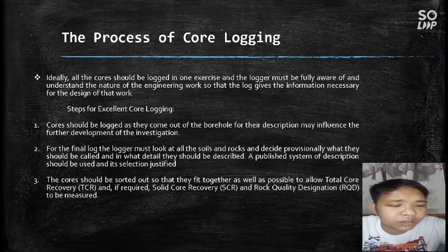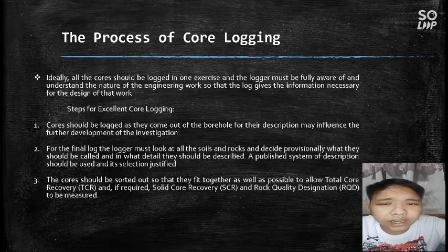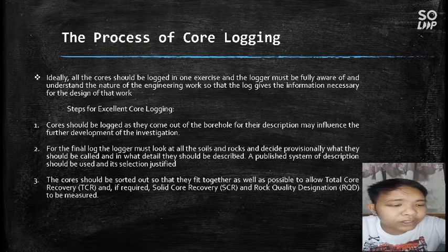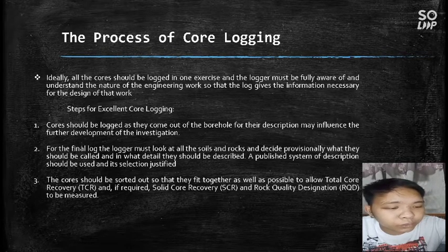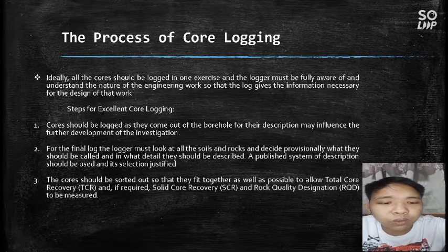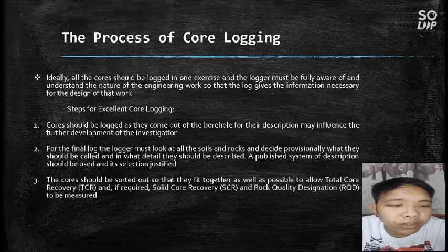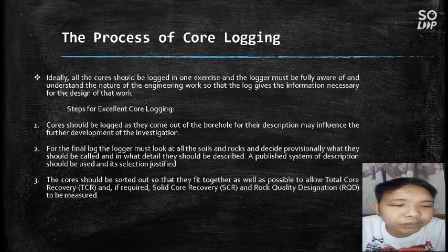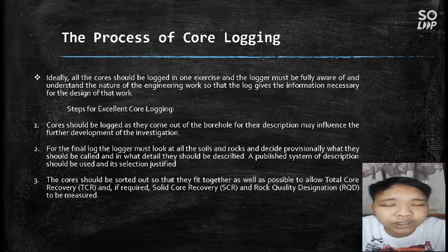Next is that for the final log, the logger must look at all the soils and rocks to decide provisionally what they should be called and in what detail they should be described. A published system of description should be used and its selection justified.